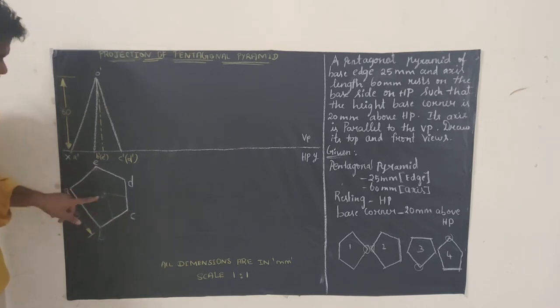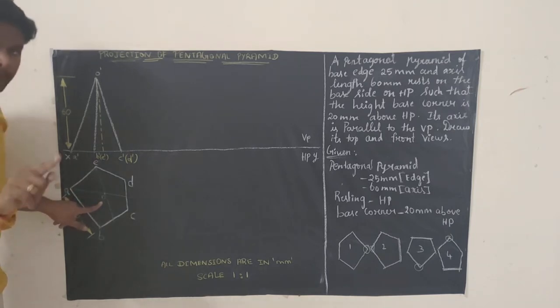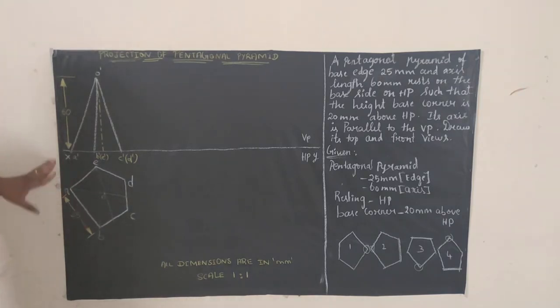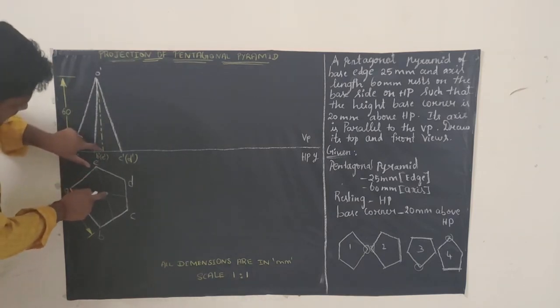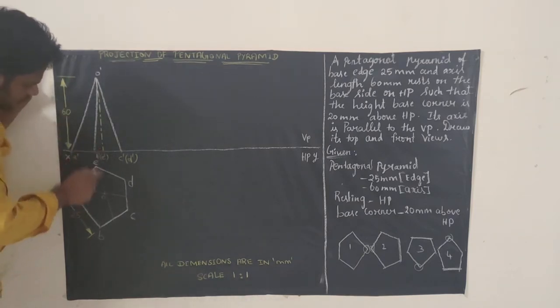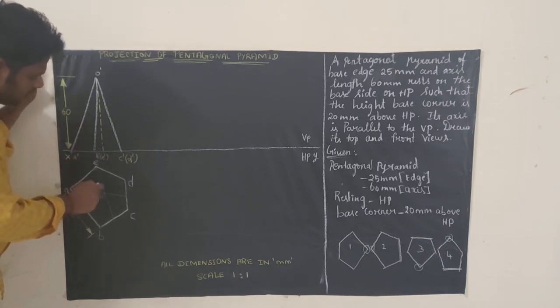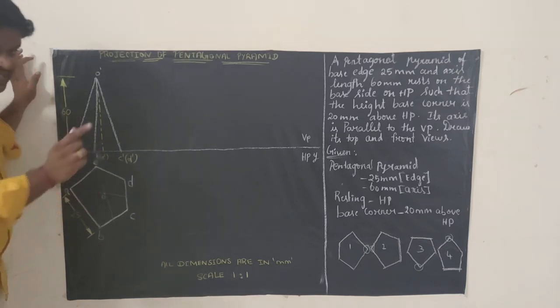So both the lines will be intersecting at one point, right? That point is called O. Mark it as O. Then keep your scale here exactly vertically. Try to get a point here. So where this O point is, vertically you have to get a point on the reference axis.